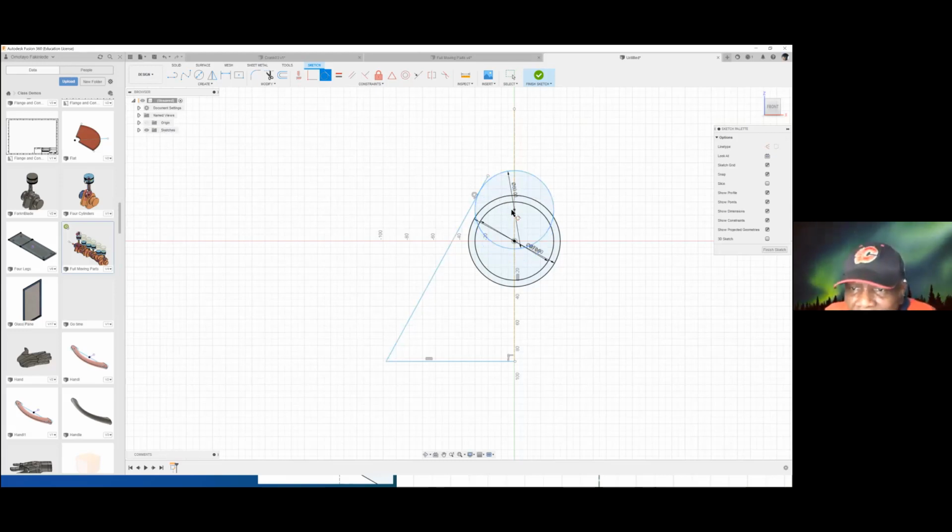Well, it's moving, but I can make this fixed if I want by just taking the distance. I can choose the distance between here and here. So let us say I want this distance to be 20, so I can just use a sketch dimension. Right now it is 24. If I say it's 20, that gives it a specific distance, so it cannot move from there. So I have everything I want.